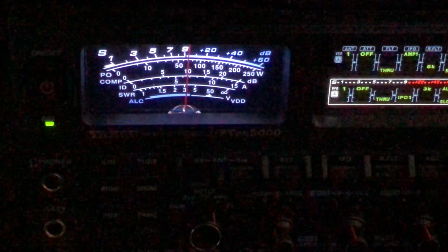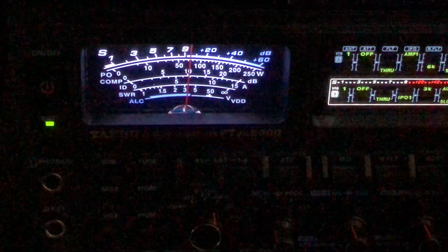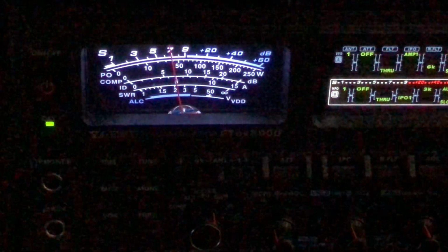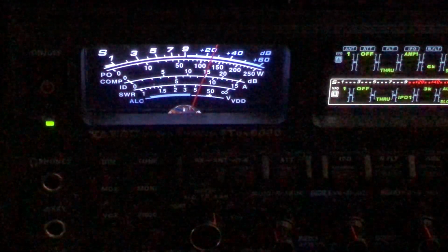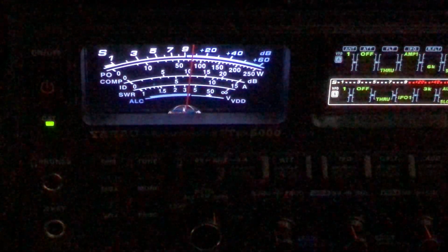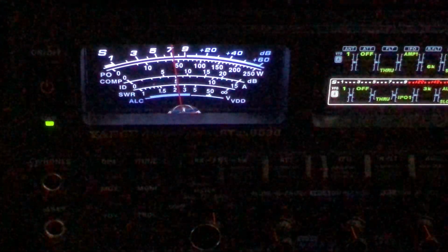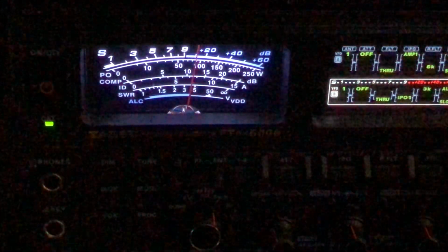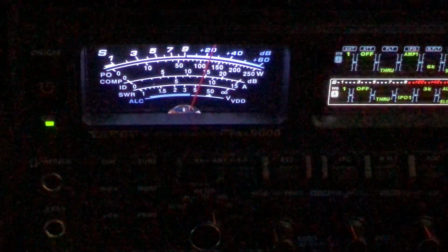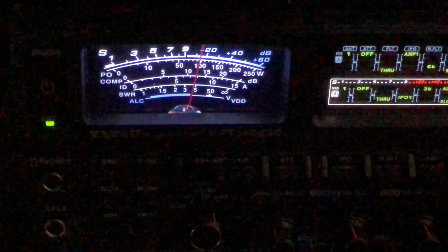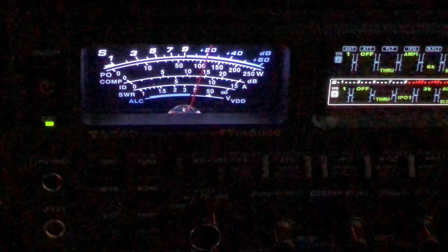So you can kind of see that it's a little bit of a diminishing return there. Well, to do that, amplifiers that can produce that level of power require 240 volts. So if your house doesn't already have 240 volts run to your ham shack, you'll have to have that done. I've done it. I've got an Elecraft KPA1500 up here that'll do legal limit, and that's the subject of a previous video, so I won't go any further on that one.